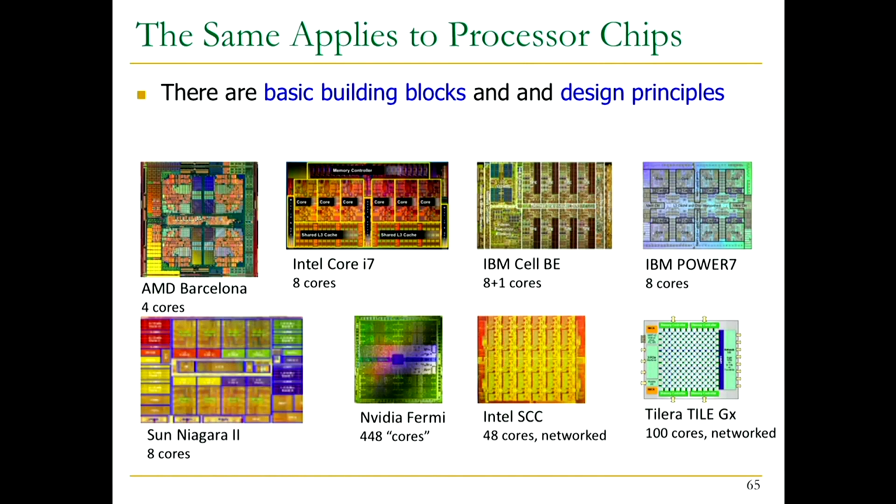There's also a video encoder and decoder inside here. It cannot do cryptographic encoding and decoding, perhaps, unless you transform the problem there, but it can do video. It can do very fast MPEG decoding, let's say, or MPEG encoding. Okay? So these chips have many components in them, and we'll cover some of these principles. But one of them you should keep in mind is specialization versus general purpose. We'll talk a lot about the general purpose design in this course. We'll talk about other paradigms also, like graphics, SIMD units, single instruction, multiple data units, and also systolic arrays, things like that.